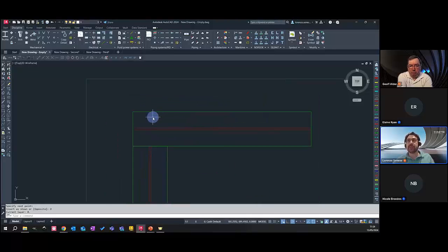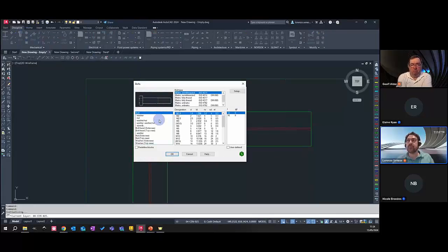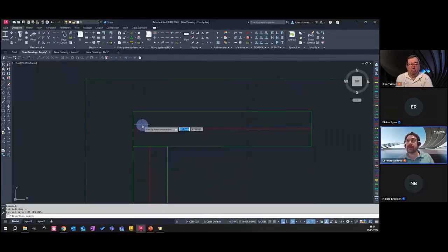I want to place a bolt connection. I can just go here inside the mechanical panel. I can see there is a hole, threaded hole, or bolt. So I can go with a bolt, for example, a bolt head top view with the washer, so I can pick the correct size. So I saw before that it was a diameter 13, so I'm just going with an M12. I click OK, and then I can place that inside my file.